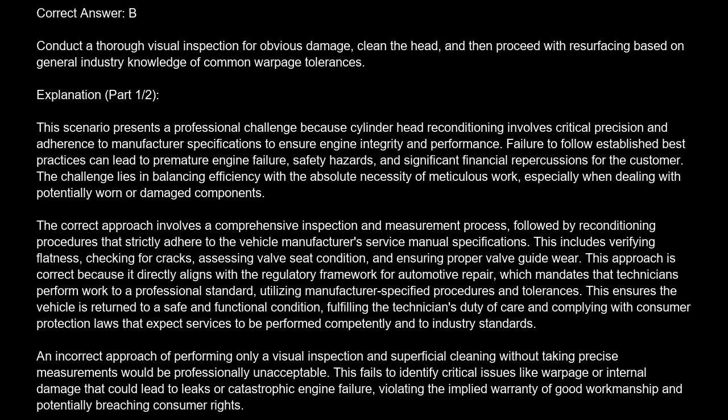Correct answer is B. Conduct a thorough visual inspection for obvious damage, clean the head, and then proceed with resurfacing based on general industry knowledge of common warpage tolerances. Explanation. This scenario presents a professional challenge because cylinder head reconditioning involves critical precision and adherence to manufacturer specifications to ensure engine integrity and performance.